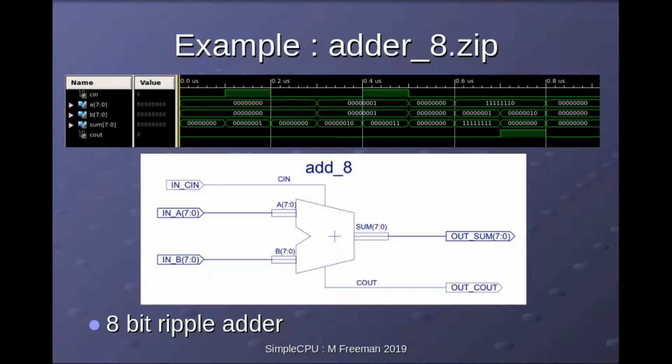Do make sure you go through these IC projects, because it'll give you good experience for the open assessment. So open up the top level schematic, you'll see this symbol here, and push through the hierarchical schematics until you finally get to that half adder. Just before we leave this slide, another good test to see if you understand what's going on is, does this waveform diagram make sense? Can you see, for example, why the carry out goes high at this point?